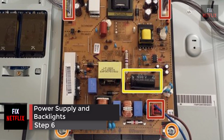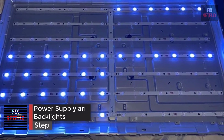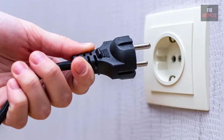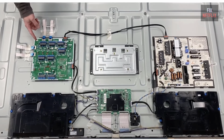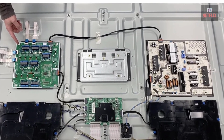Step 6. Power supply and backlights. You can check the power supply and the backlights in one swipe. Make sure the TV is unplugged. Open the back. You may need to remove the base to access all the screws that hold the back on. Disconnect the black cable between the main board and the power supply board.